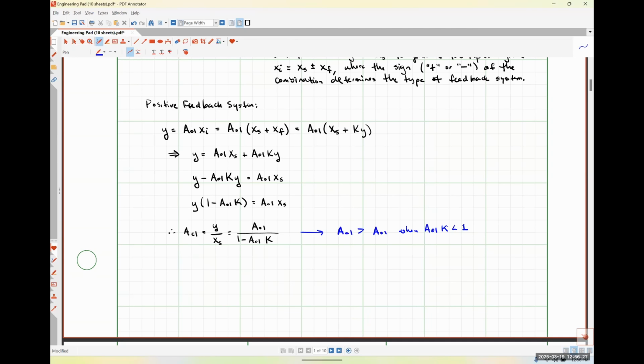So whenever we have a positive feedback op-amp circuit, we know definitively the output of that system is always going to be in saturation. We are either going to be at VCC plus, or we are going to be at VCC minus, because the linear range of the system is so incredibly small, it practically does not exist, okay?